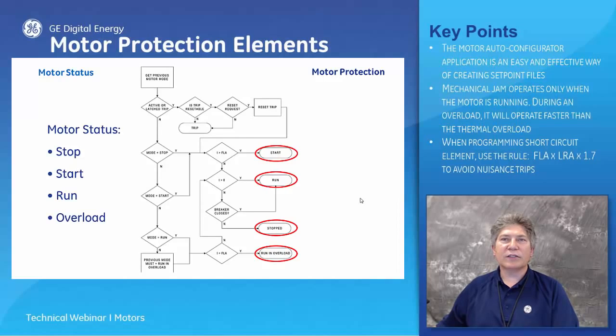Motor status. If no auxiliary contacts from the starter are wired to the relay, the relay will assume the motor has stopped if the phase current is less than 5% of the CT primary current, and will detect a start condition when phase current is sensed after a stopped motor condition. If the motor idles at 5% of CT, several starts and stops can be detected, causing nuisance lockouts if starts per hour, time between starts, restart block, or backspin timers are programmed.